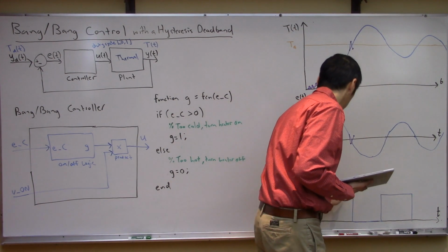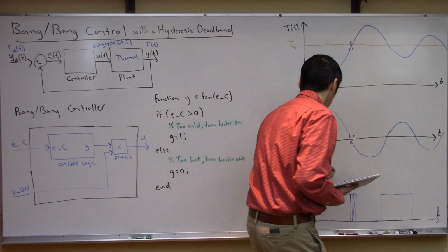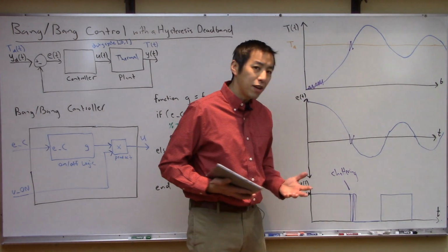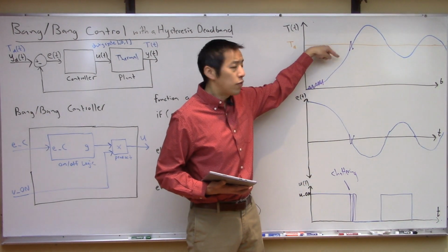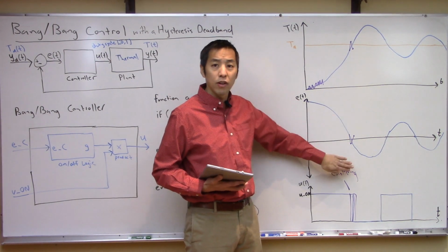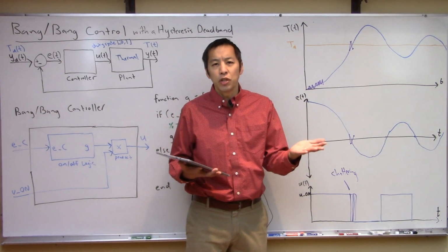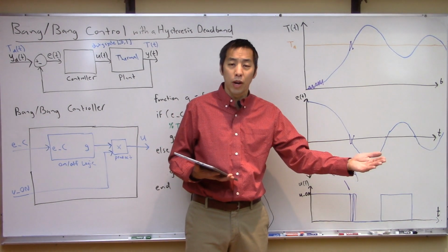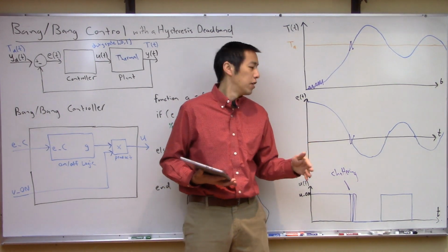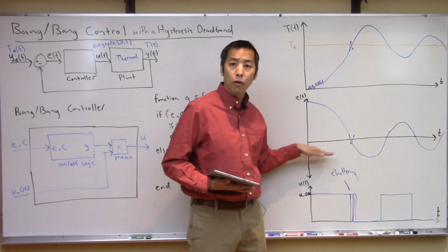So your control signal is going to flip-flop, and we get this chattering effect. We talked about this last time. If you think about this long enough, this chattering comes from the fact that you've got this noise which is rapidly bouncing you positive error, negative error, positive error, negative error. The controller is being wishy-washy. It just hasn't committed one way or another. That's why you get this chattering. It's like, oh, I don't know, I want to turn it on, turn it off, turn it on, turn it off, because the noise is bumping you above and below the 0 error line.